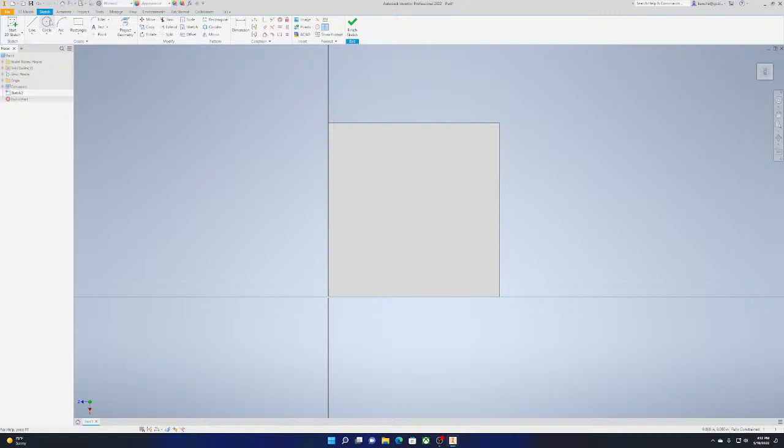Okay, and now I want to cut a circle out on every face. So I only need to do this 3 times because it'll go all the way through. So I can do the circle. But you can see right here that I don't actually know where the center of my object is. So I can escape, and we can use the line tool to figure that out. I can click the line tool, and you can see when I get to the midpoint, it snaps. So 0.5. I can click there, and then my line has been created.